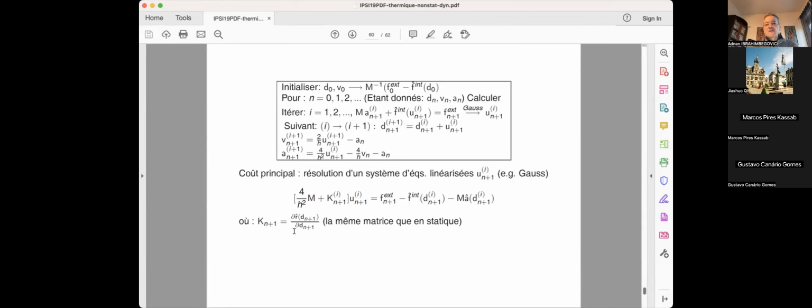The experience that I had is this: in my thesis, I studied frictional contact. We have a non-associated type of plasticity and structures that can slide on the support, to reduce the effects of maximum dynamic loads. When I studied dynamic contact, it was always easier to deal with. Then I realized that before you start dynamics, you have the history, you have to take into account the statics. So I suppressed the inertial effects, and I had much more trouble converging when I did not take dynamics into account.